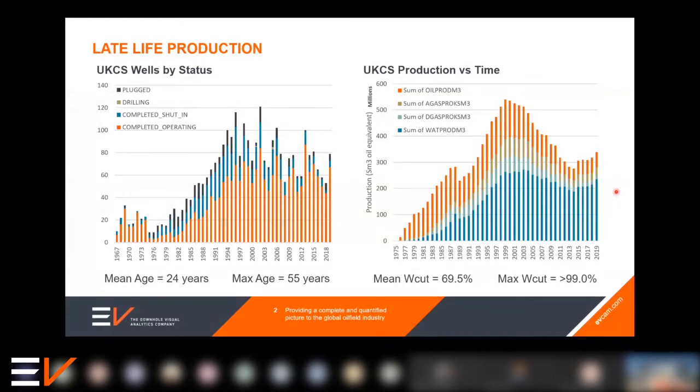The highest producing well, and again, this is not an injection well, so don't be tricked by that one. This is a genuine hydrocarbon producing well. There are some that are sitting over 99% water cut. So with that, you've got challenges in managing the chemistry there. This water brings with it potentially corrosion-enabling materials. It could carry oxygen, it could carry minerals, dissolved gases, and even things like sediments coming out of precipitation. It could bring sand with it. So again, this challenge of keeping the wells healthy gets more difficult as time goes on.